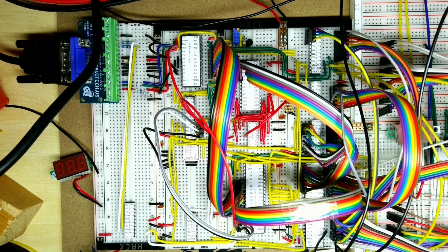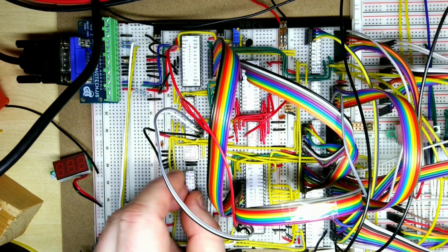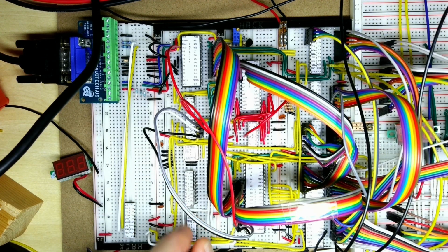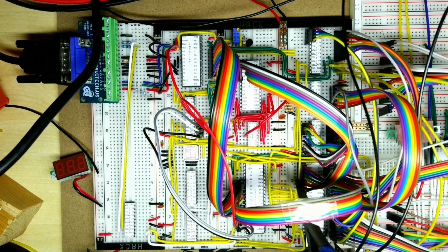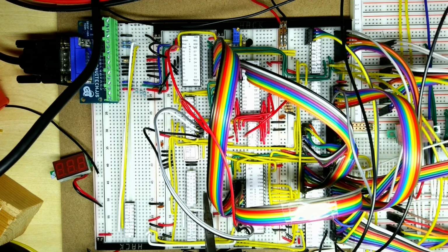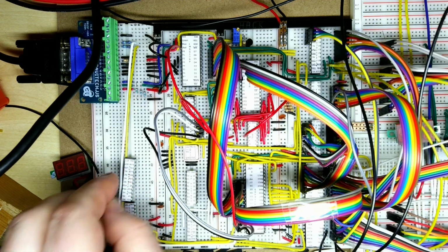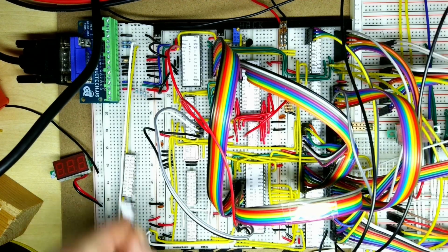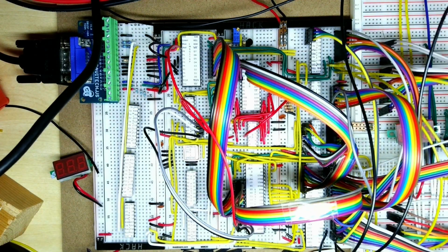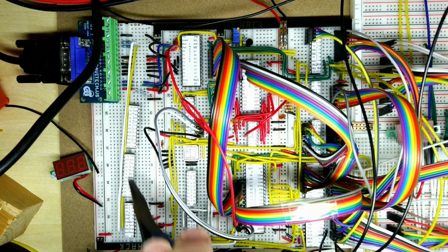So I've already put the labels on the chips. The attribute latch is going to be going into this position here. It's going to need to have a feed, probably using a DuPont cable with the 8-way connectors on it, from the output of the video RAM over here over to this side. We're then going to put the video output PLD down here. We'll probably need to move these horizontal sync, vertical sync cables, and then the attribute multiplexer is going to be going over here. Again, we need to move it over a little bit, and then there'll be quite a few signals going backwards and forwards between the control port here and the various things here.